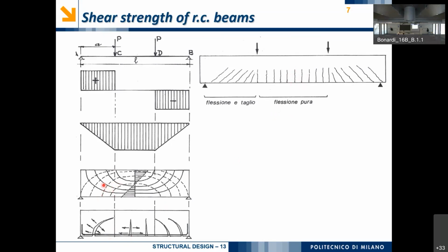But in the lateral region, this behavior is no longer horizontal, and so we have some inclination of all these lines. And this inclination of all these lines is orthogonal to the direction of all the shear cracks that will appear on the beam. Okay? So basically what we get is that we will find some portions of the structure that exhibit diagonal cracking.